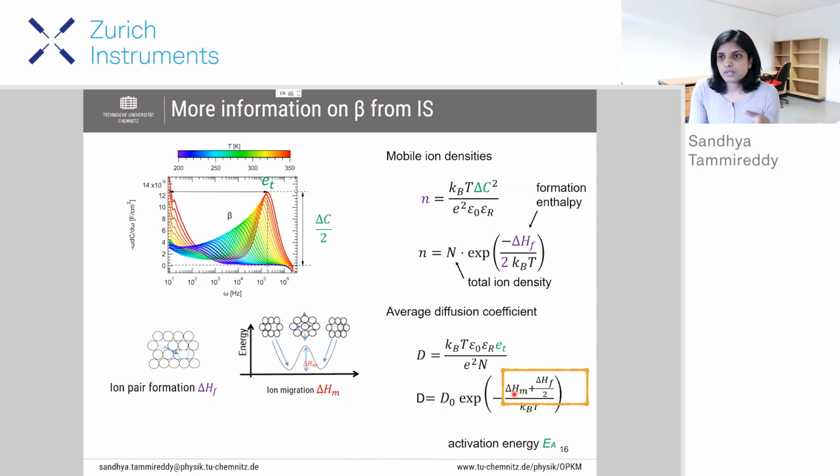How can we use these three parameters to understand the ionic defects better? Towards that, we started looking into the total ionic defect density. As we discussed, DLTS indeed helps us to separate the positive and negative charges as long as we know the background charge. If we know it's a p-doped or n-doped material, then we can separate.